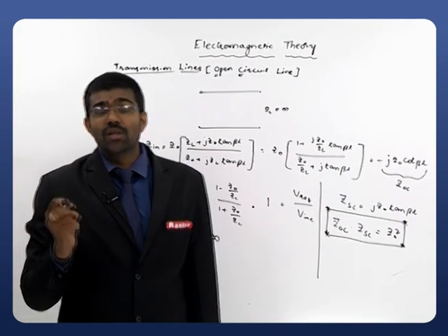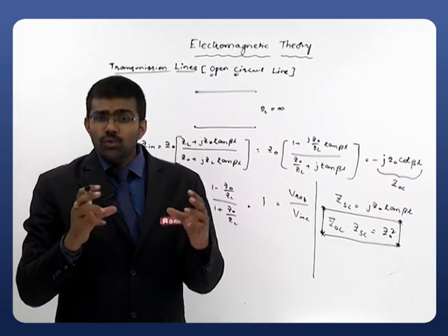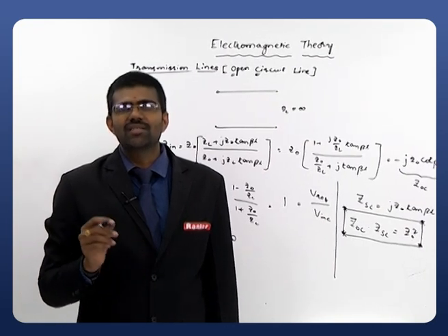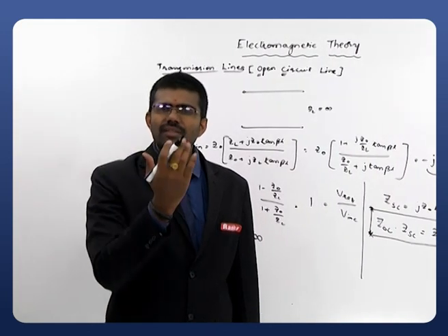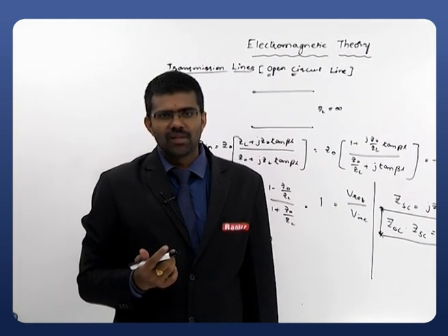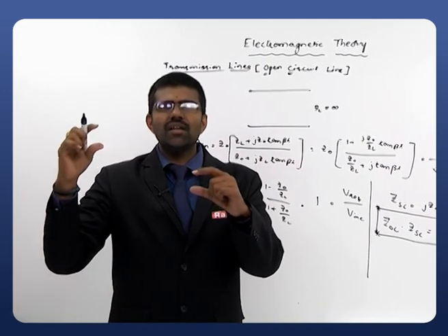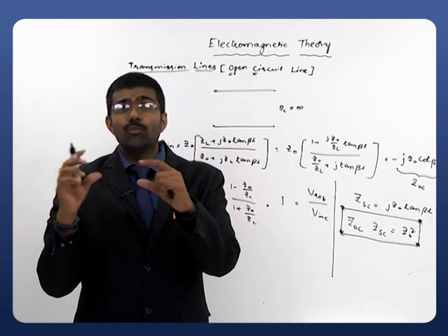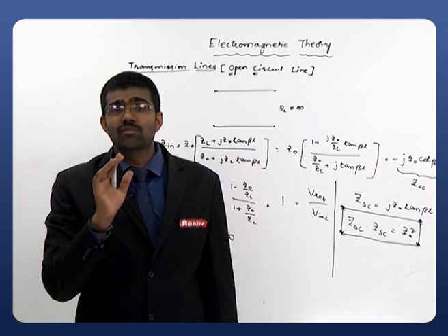Then if we require very good signal transmission, or if the signal is to be transmitted through the load, what is the condition? That case is called a matched impedance load. Matched impedance means the load is perfectly matched with the transmission line. The transmission line characteristic impedance is Z0. The load I am considering is ZL. If these two are matching, then the maximum propagation must be there. That is our assumption. Now we will observe whether the propagation will be there or not.